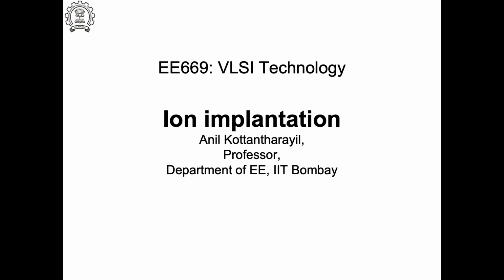So if you now look at ion implantation, how do I actually study this? One software you can see is SRIM, which is very widely used for ion implantation of ions into amorphous materials. It is used not just for VLSI, but for any ion implantation processes that we explore.